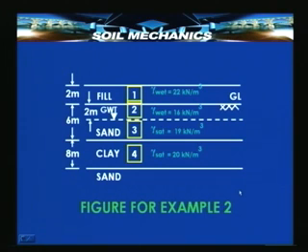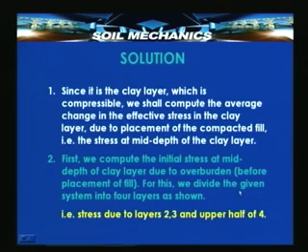Let us see how to compute the initial state of stress, or how to solve this problem in general. The solution consists of a series of steps. There are as many as 8 steps, as you will see shortly. The first step is understanding the problem. Since it is a clay layer that is undergoing compression, the compression in the sand layers is not of any consequence. We shall compute all stresses, all stress changes and the void ratio changes in the clay layer only.